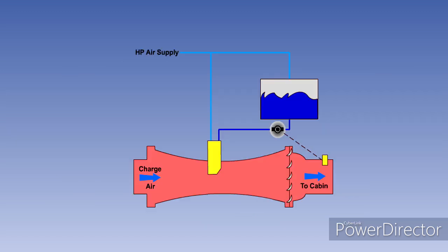The water separator does most of its work in low-altitude humid conditions. However, at the high cruising altitudes used by modern transport aircraft, the air is very dry. When operating at high altitudes for long periods of time, it may be necessary to increase the moisture content of the conditioned air from the 1 to 2% relative humidity of the ambient air to a more comfortable level. The component used to do this is the humidifier, a typical example of which is shown here.